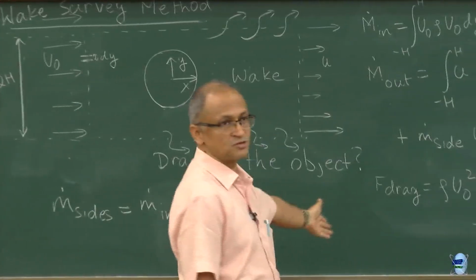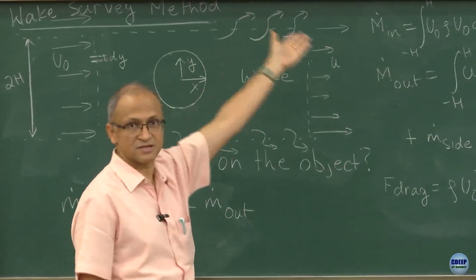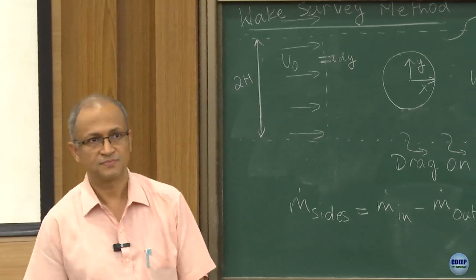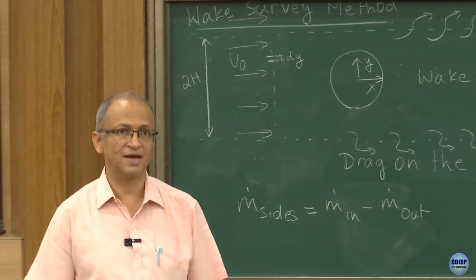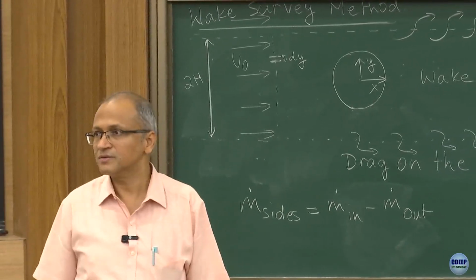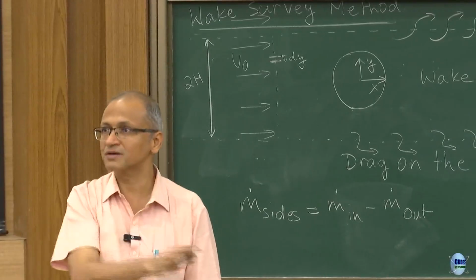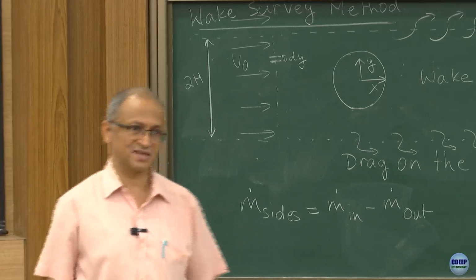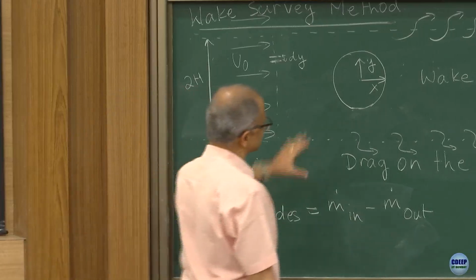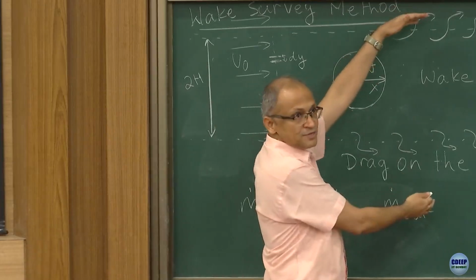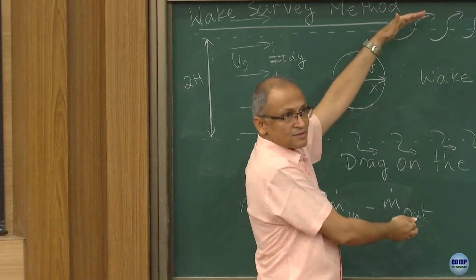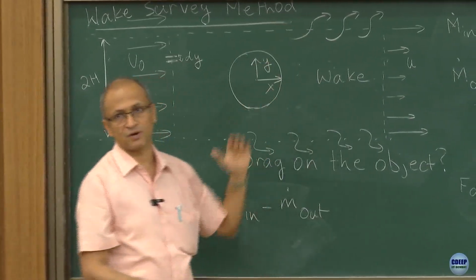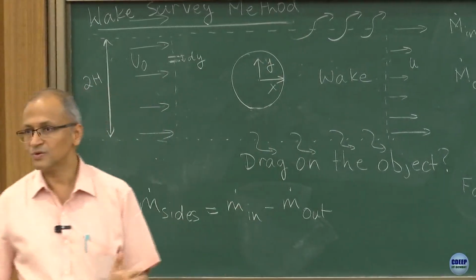Of course, we have not talked about how to find forces along the vertical direction. Can we find forces along the y direction here? Yes, in principle there is nothing wrong with that. Whatever we are doing along the x direction, we will have to do along the y direction. In this case, that exercise is futile, because of symmetry, there will be the same amount of mass on both sides, and therefore these two momenta are also going to cancel out. So there is no point.